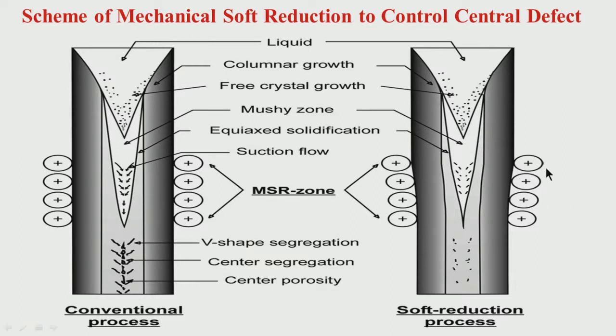Look at what is happening here. This was the original thickness dimension. You are putting some additional pressure in the final solidification zone. So, what is happening? The thickness is slowly coming down, not in one step, not at only one location, but slowly. That means there is a gradient in how the thickness is coming down. You are putting pressure in the rolls, you are decreasing the distance between the rolls in these areas.